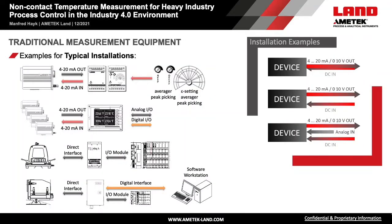These are typical installations of such analog traditional measurement equipment, starting with a typical analog instrument or pyrometer, outputting the temperature value via linear 4 to 20 milliampere output, and receiving the 4 to 20 milliampere input, for example, to receive and set the emissivity which was chosen on the analog controller installed in the switch cabinet.